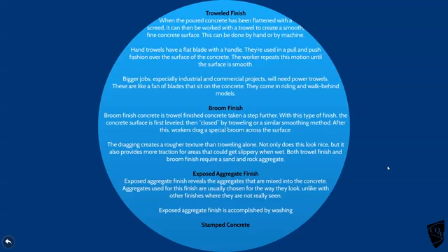floating, what's it called? I can't remember, the concrete float. It hovers over the surface and polishes it flat while it's still wet. You can use a broom finish, a stiff broom, and that gives a rougher texture, which gives it more grip, so that's good for walkways and paths. Exposed aggregate, you can do that one. That can either be done with an acid wash, or you can grind it down. Polished concrete, you see it used in a lot of places now, where they've cast the concrete and then polished it, so all the aggregate almost looks like marble if they do it well. Stamped concrete, you get that on driveways where you stamp patterns into it.